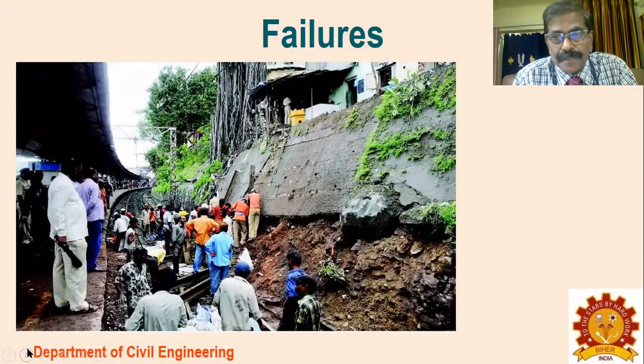If it is not done, if you have some standard foundations that you just adopt at all the sites without understanding what exists in the underlying soil, or what is the soil below the loose rock or something like that, then there could be a possibility of collapse, as you see in this figure: a collapse of very big roadways that have come down.